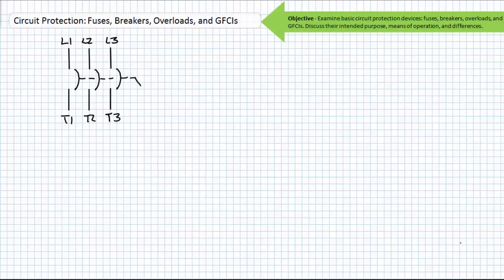Industrial power isn't normally limited to single sources, so sometimes you'll see a 3-phase circuit breaker. It's essentially the same thing as three 2-terminal single-phase circuit breakers all linked together. We'll discuss the details of three-phase AC later, but proper operation of a three-phase system normally requires a balance between the three independent sources. Consider the coordination offered by a single three-phase circuit breaker and contrast it to three independent fuses servicing three individual phases.